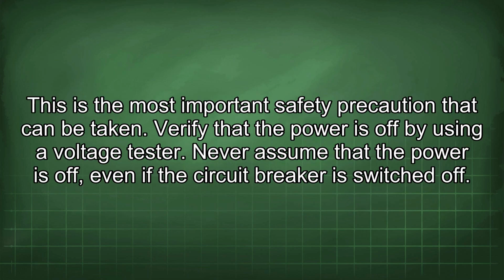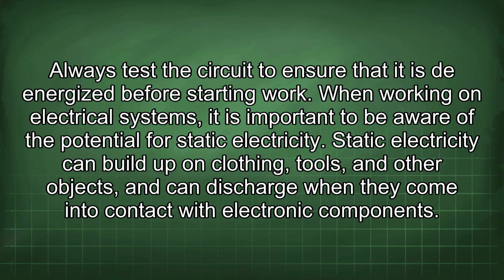When performing electrical work, always disconnect the power before starting. This is the most important safety precaution that can be taken. Verify that the power is off by using a voltage tester. Never assume that the power is off, even if the circuit breaker is switched off. Always test the circuit to ensure that it is de-energized before starting work.